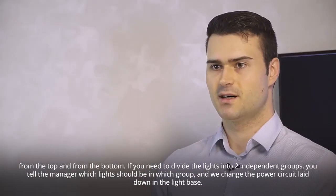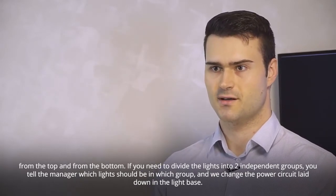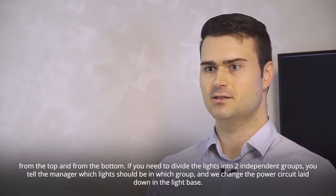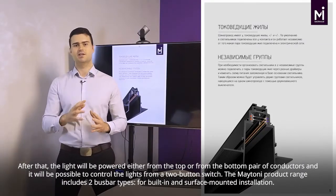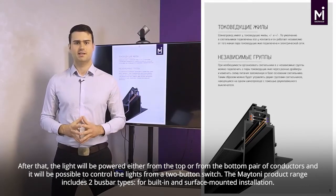If you need to divide the lights into 2 independent groups, you tell the manager which lights should be in which group, and we change the power circuit laid down in the light base. After that, the light will be powered either from the top or from the bottom pair of conductors, and it will be possible to control the lights from a 2-button switch.